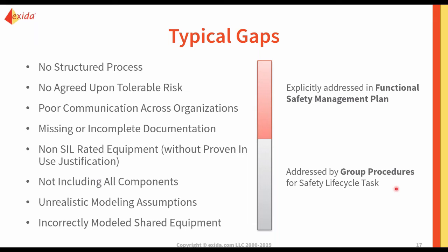It provides the specific technical guidance for the policies and procedures that are followed while, say, executing your SIL verification. So understanding what the boundaries of accepted proof test coverage would be, where your failure rate data comes from. All of these things are fundamental for ensuring that the task is completed correctly, and they all fall within the overall umbrella of functional safety management.